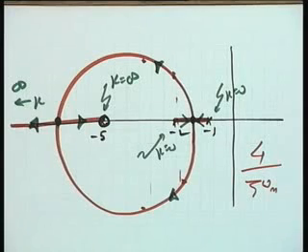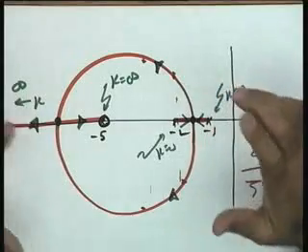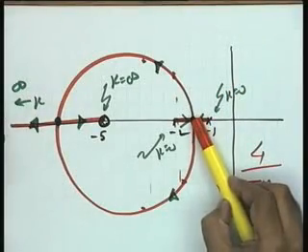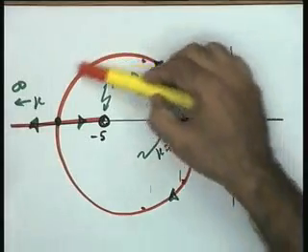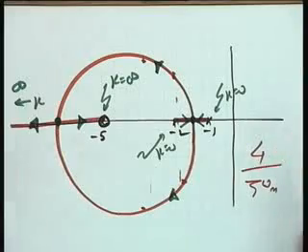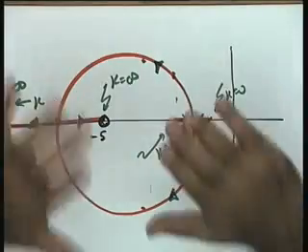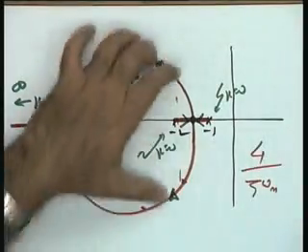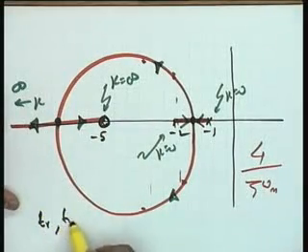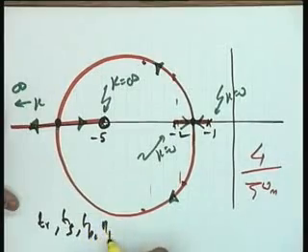So it means the system becomes faster, it settles down faster as the value of k increases from this repeated roots value, where it is critically damped, to the values where it becomes under damped. So this way the root locus plot gives me the picture about the total behavior of the system. So it means now if I have this sketch and all those TR, TS, TP, MP, etc.